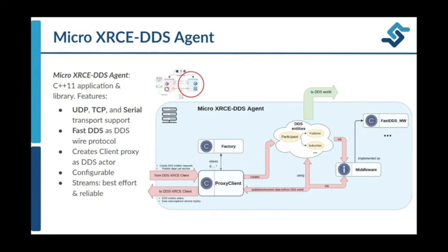So this is why before I was saying that even though this protocol relies on a client-server architecture, ultimately it allows benefiting from the full publish-subscribe architecture of DDS, because the client ultimately is acting as a full DDS player thanks to the agent. Okay, and the agent does so by creating a client proxy that basically acts on behalf of the client with full DDS functionalities.